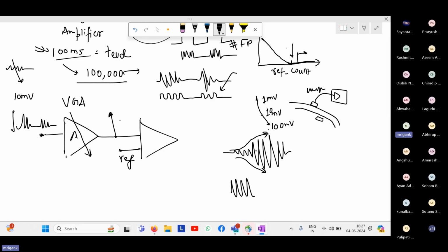After that, when the signal is completely high, then it will completely produce VDD or ground, because when the signal becomes very large, the amplifier output will saturate, right? So if the input itself is fluctuating by a large amount, the signal to the amplifier itself is pretty big, then the output will fluctuate completely to VDD or ground, VDD or ground. That's what will happen. So initial pulses will be smaller, but finally it will completely go to VDD or ground.